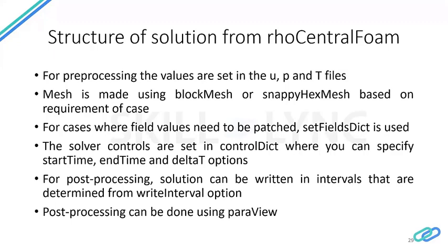The solver controls are all defined in the controlDict file as we saw earlier in the system folder. In here, you can specify your start time of solution, end time of solution, the write interval, and so on and so forth.